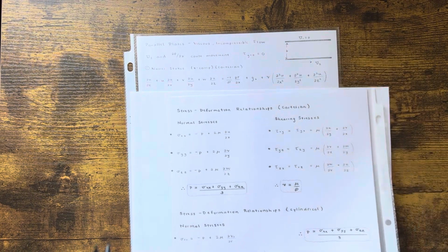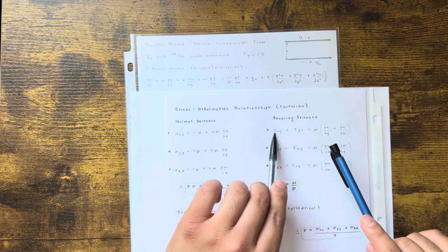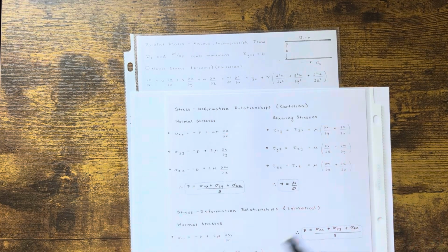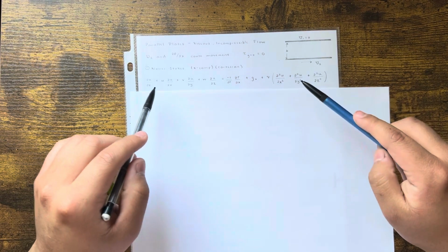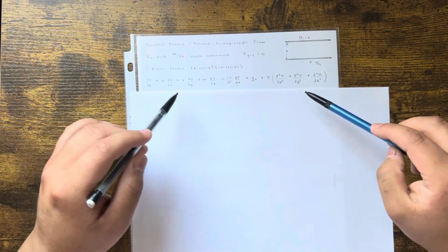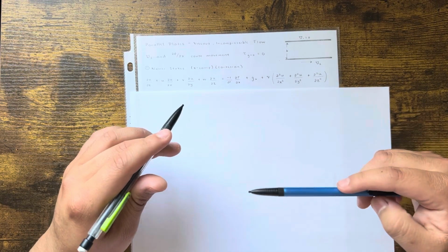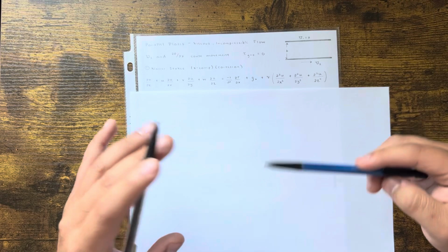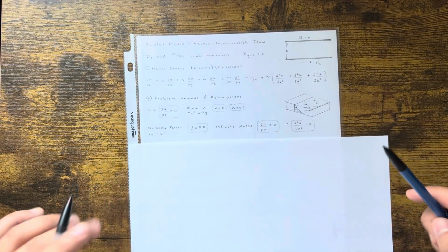Then after, we're going to end up using the shear stress, and when we get there, I'll show it again, but we're going to be using tau xy because we're in the X and Y system. So the equation looks scary, but it's really not. You start off with this massive equation, and then you just start canceling out a bunch of terms based on assumptions and problem givens or problem knowns. So that's my step 2. This is what I like to do.